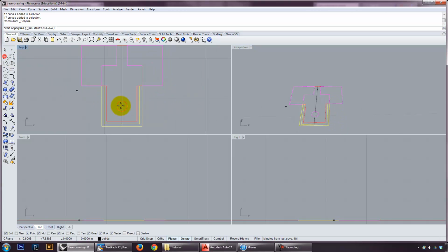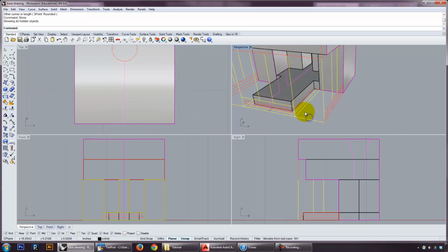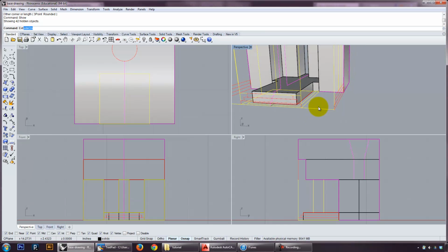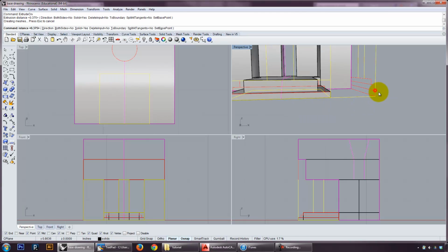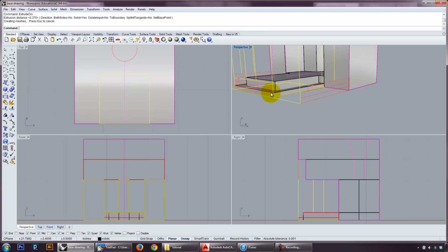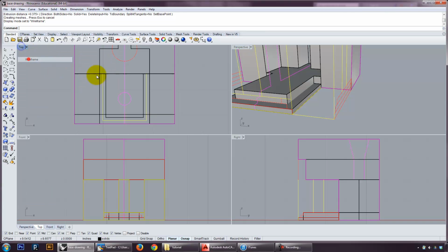Okay, so the other two pieces I'm going to draw. I'm going to draw a rectangle for this set of stairs, and a rectangle for this set of stairs. And then I'll turn these back on. I'll use those lines. I'll extrude those lines. So the first one, extrude curve. Notice how I've got the same thing drawn in multiple drawings. I could snap to here, I could snap to there. It doesn't really matter. Okay, and if I go to wireframe, so I can pick this line.